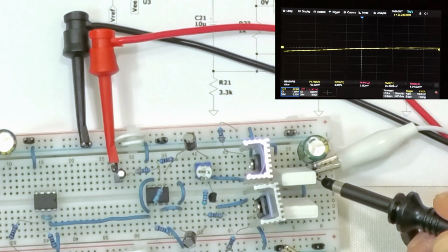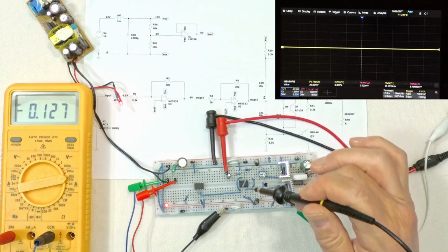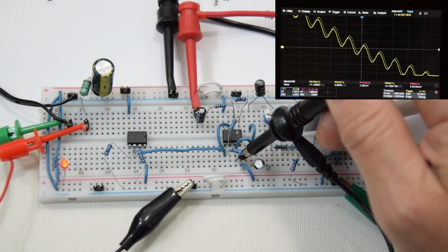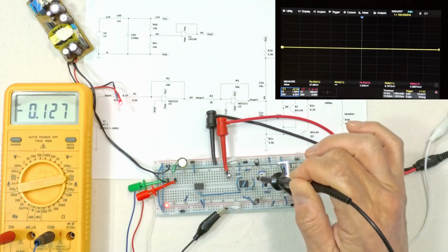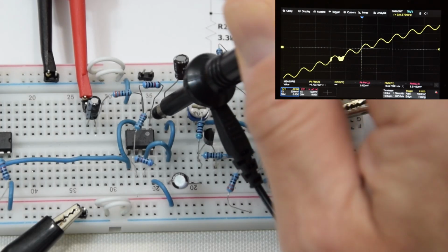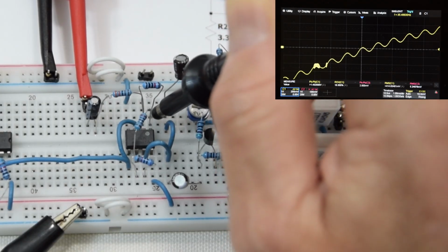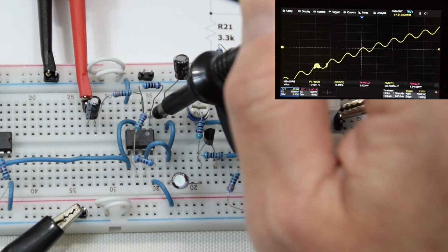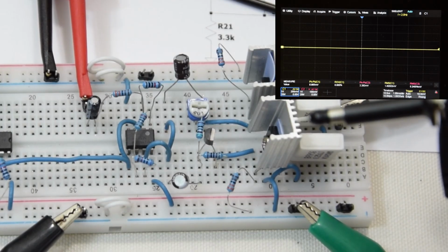Well, this has nothing to do with a sine wave. Let's see what the output of the op amp looks like. Well, not good. Let's see what the output of the first stage of the op amp looks like. Well, that looks like a sine wave, but not in the right way. As you can see, it's not level. So that makes me think this is a power supply issue, as the sine wave is reproduced nicely.